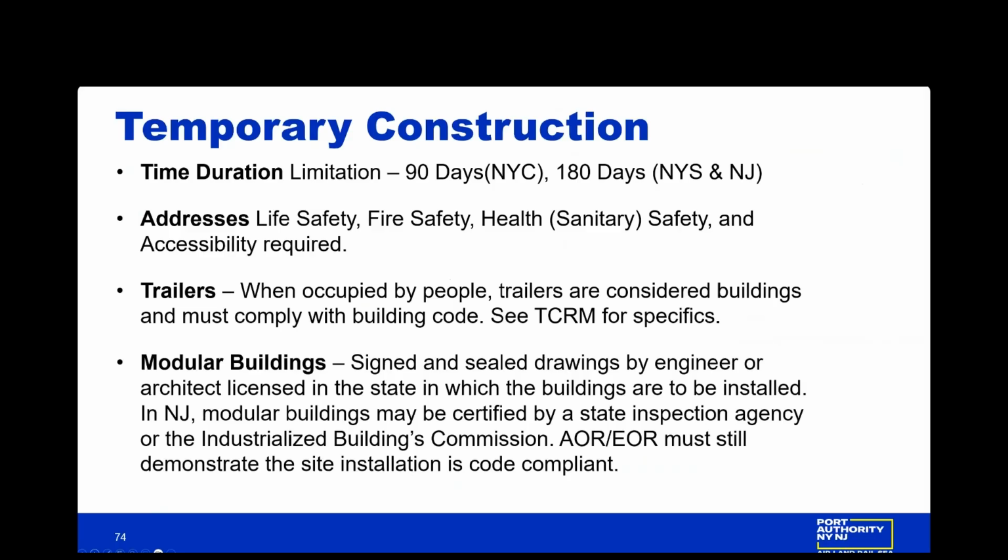We do temporary construction and events. The time duration is shown here, 90 days for New York City, 180 days for New York State and New Jersey. We address life safety, fire safety, health, and accessibility. Trailers, where occupied by people, are considered buildings and must comply with the building code. We have a full list of that compliance criteria listed in the TCRM to help you answer your questions for that particular project. Modular buildings, they must be submitted with signed and sealed drawings by an engineer licensed in the state. And in New Jersey, modular buildings can be certified by a state inspection agency. Next, please.